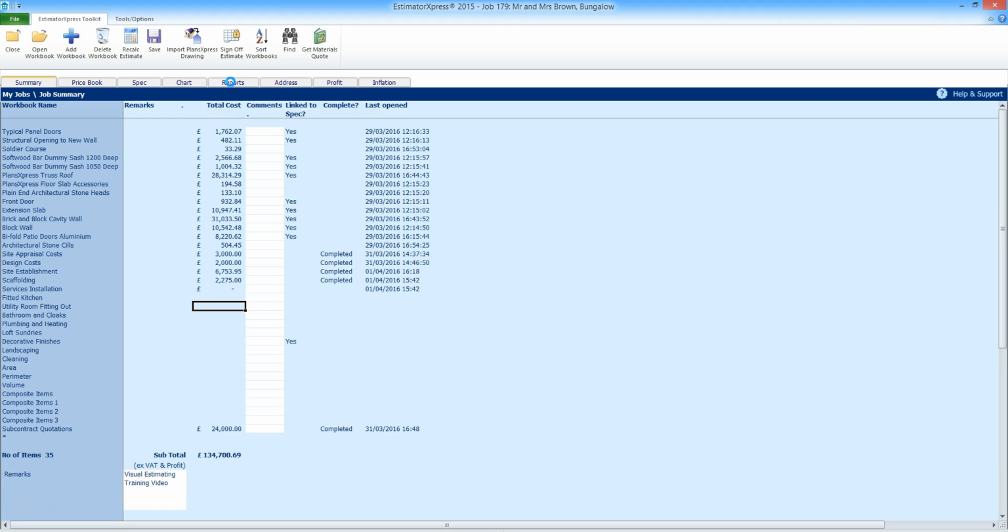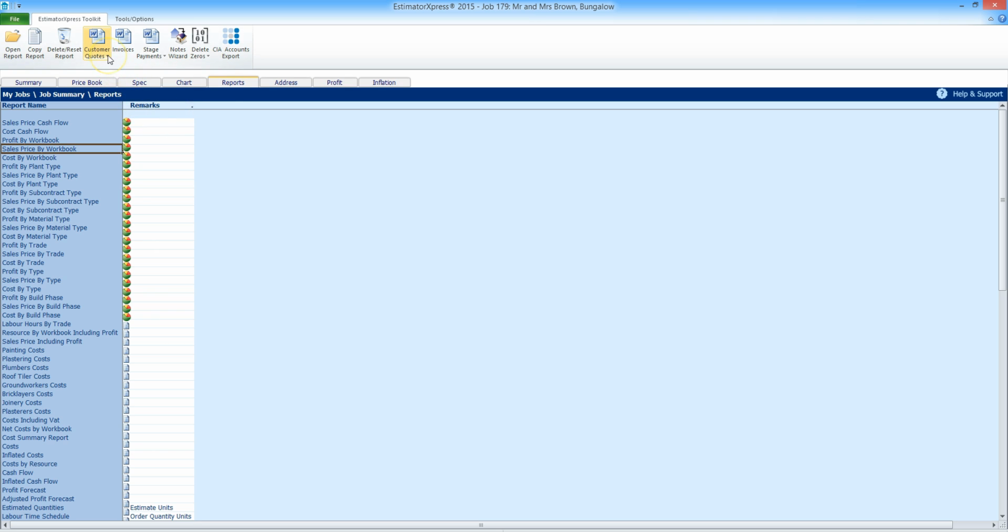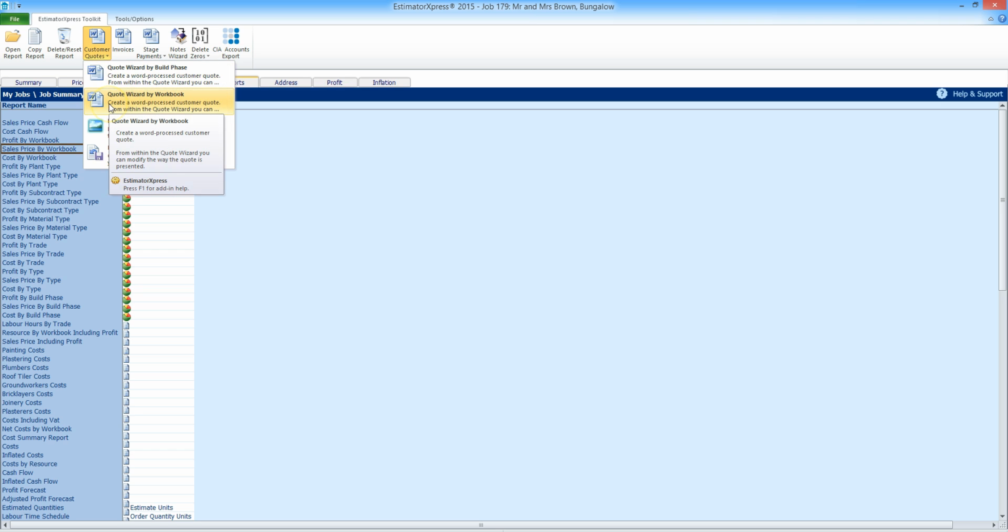Click on the Reports tab, select the customer quote, and choose either Quote Wizard by Build Phase or Quote Wizard by Workbook.